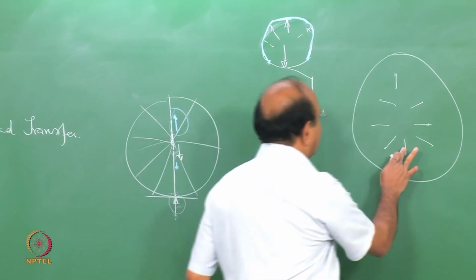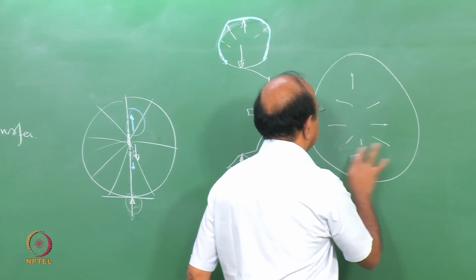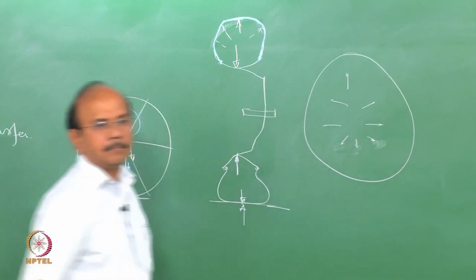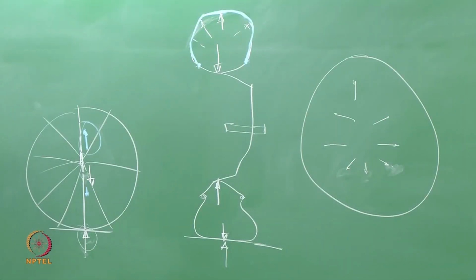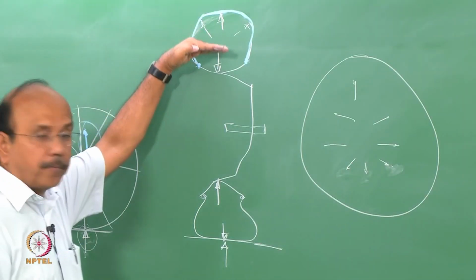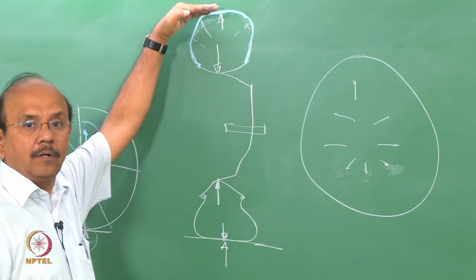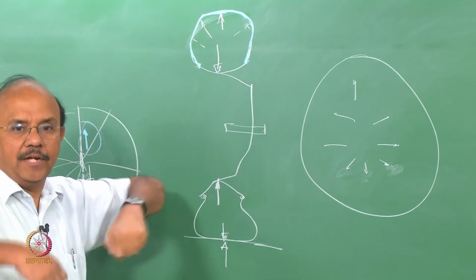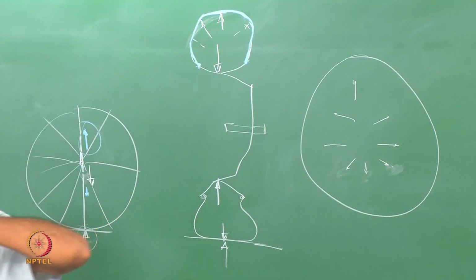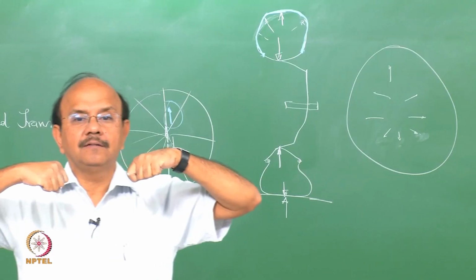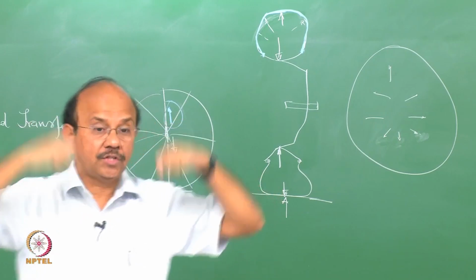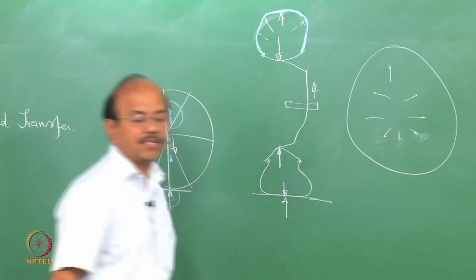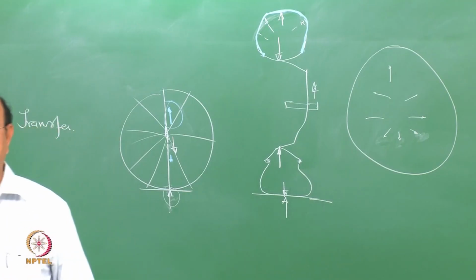So that now reduces. On the other hand, this pressure gives more, or this is more than this now, and so the side walls have the tension to pull the rim, and through which it pulls or gives the reaction to the axle.